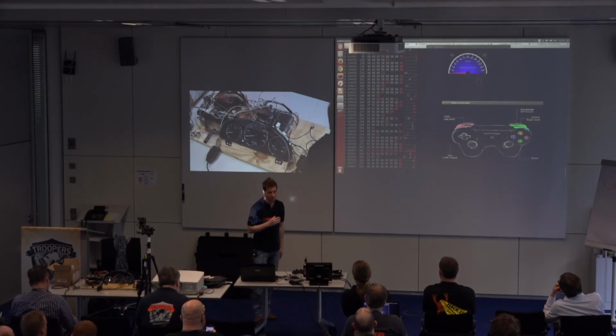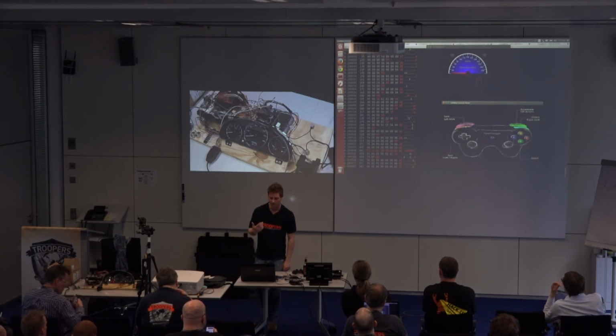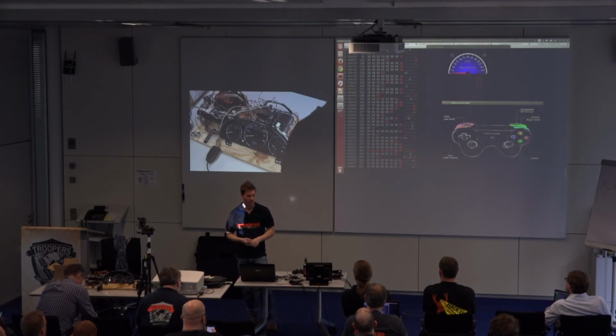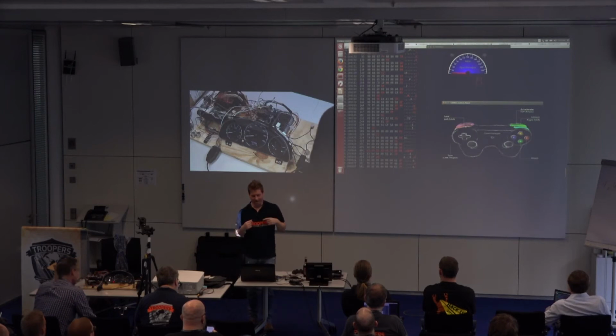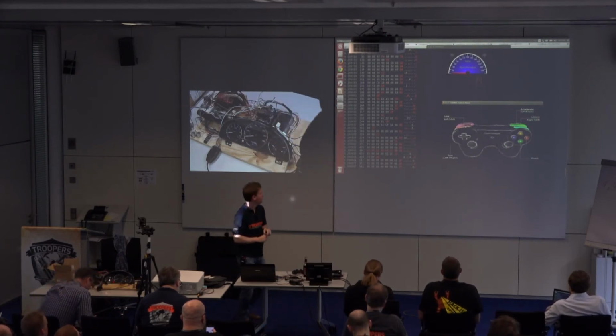If you flood the bus too quickly, and just say you don't put a delay in your code and you just blast it, you can shut the engine down. Typically what will happen is the engine will go into limp mode, which is like a 35 mile per hour kind of mode. Oh, which should bring up a point that you shouldn't do this while you're driving. But if you did, that's what would happen, usually.